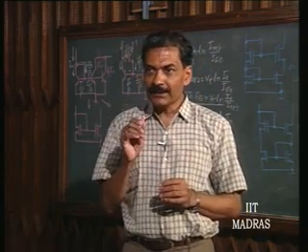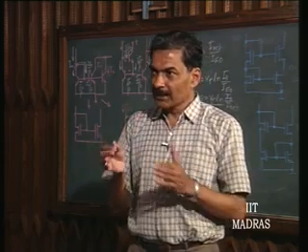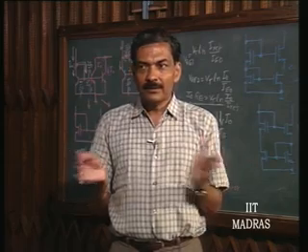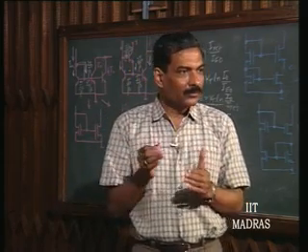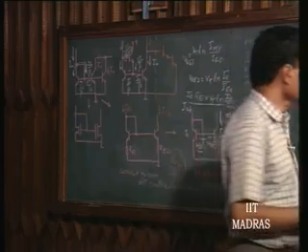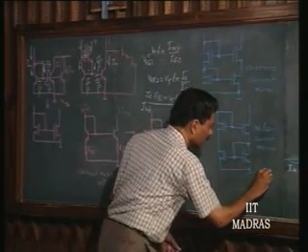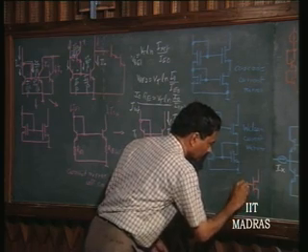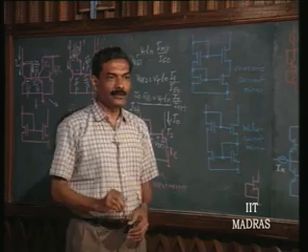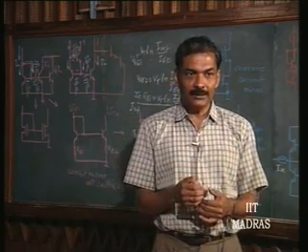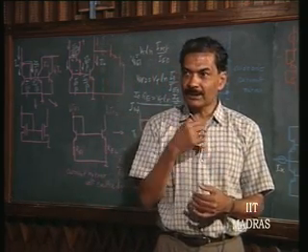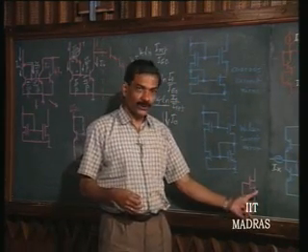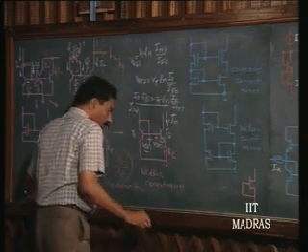As far as JFET is concerned, JFET is basically a depletion type. You cannot have a current mirror using JFET. With JFET you can only have a current source of the type we discussed yesterday, wherein we just short the gate and source. If you want a different current in this case, or if you want higher output impedance for this current source, what can you have? Like emitter degeneration, you can have a source degeneration resistance put here.